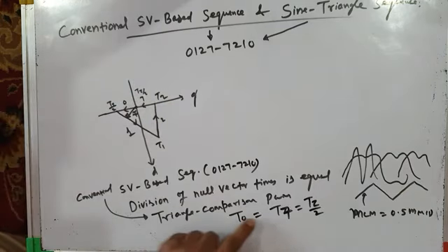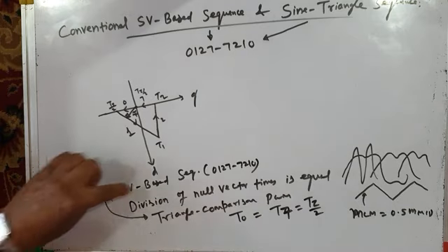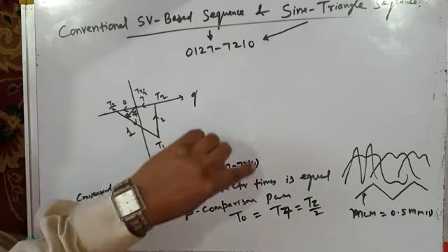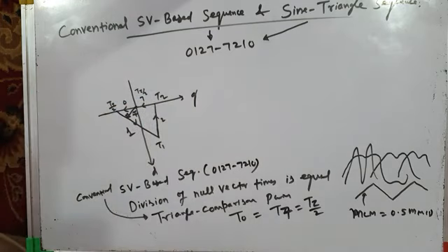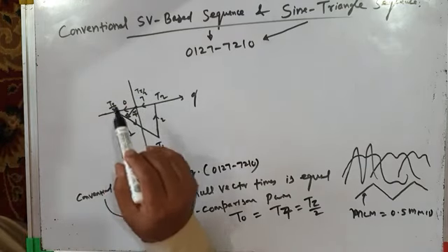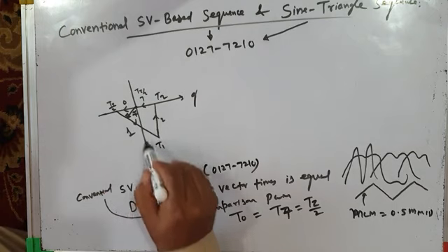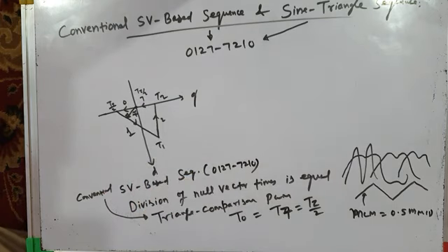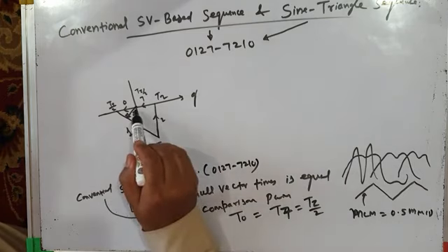Okay, so this can be done by injection of common mode signal, or if you use space vector approach, in conventional space vector approach, automatically it does. And now you can see, as far as d-axis ripple is concerned, this is along d-axis. I have already told you we have fundamental flux, so we are not bothered about d-axis. We are bothered about q-axis ripple.